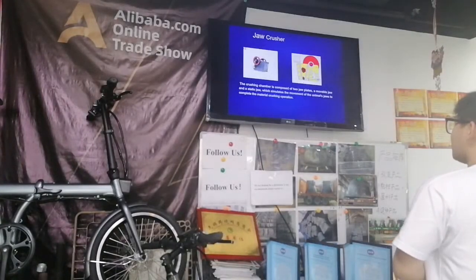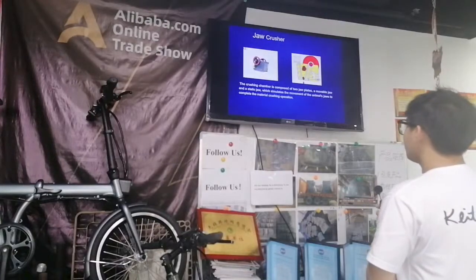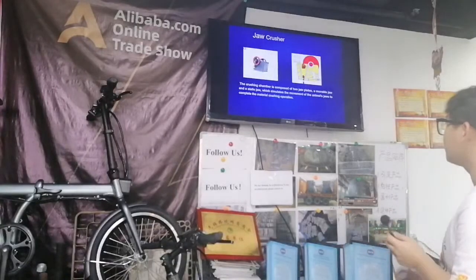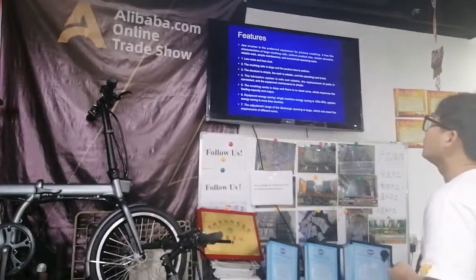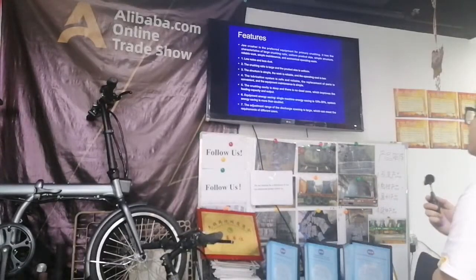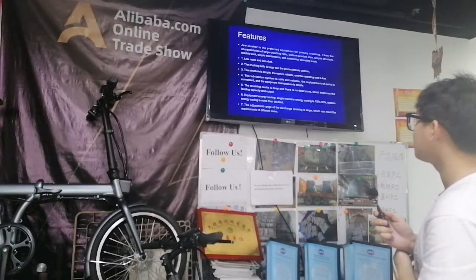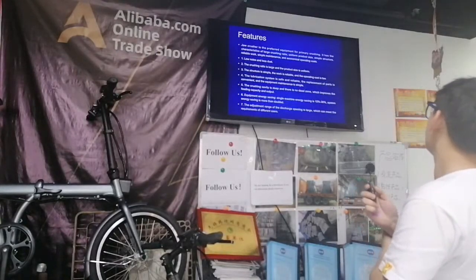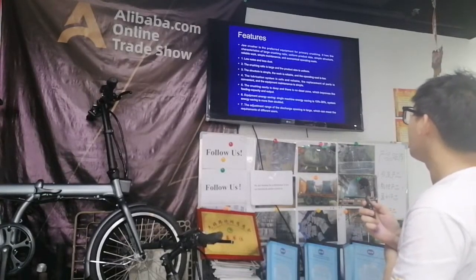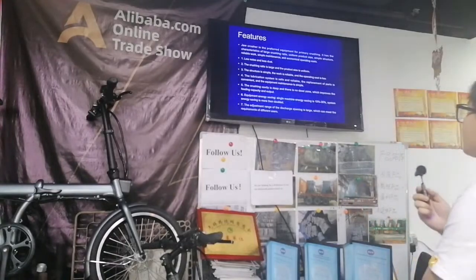The crushing chamber is composed of 2 jaw plates, a movable jaw and a stationary jaw, which simulate the movement of an animal's jaw to complete the material crushing operation. The features: the jaw crusher is the preferred equipment for primary crushing. It has characteristics of large crushing area, uniform product size, simple structure, reliable work, simple maintenance, and economical operating cost. Low noise and less dust.